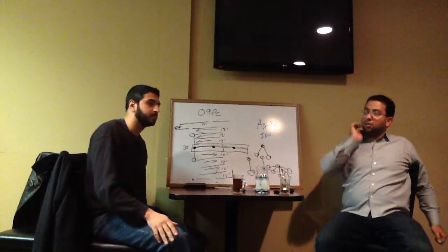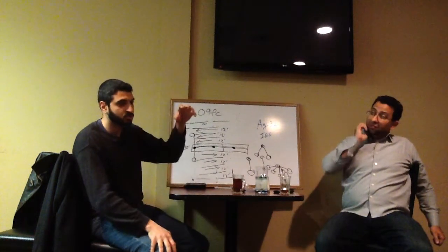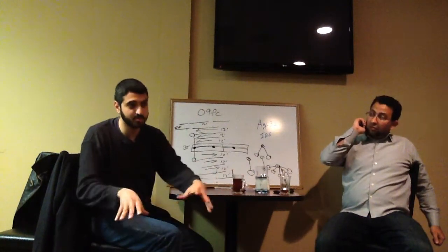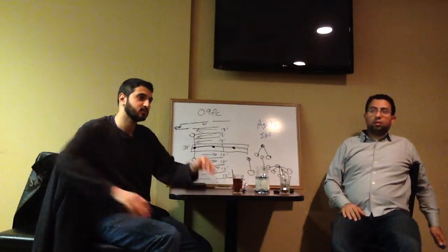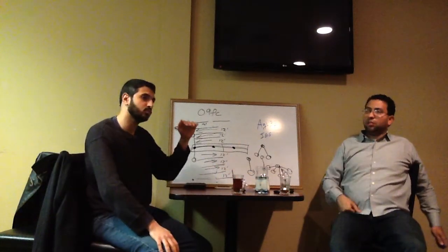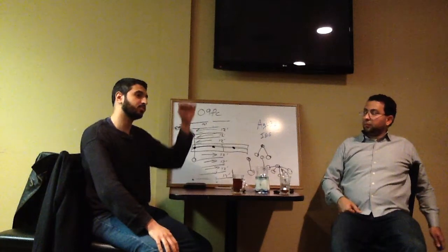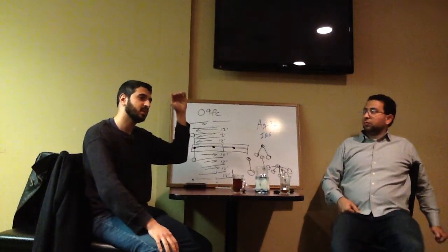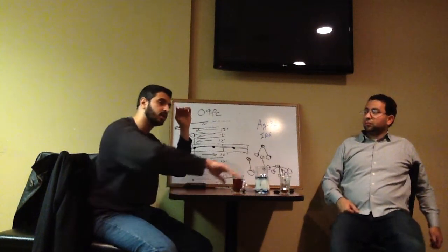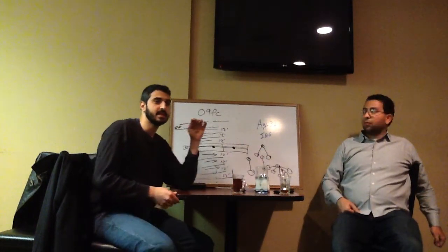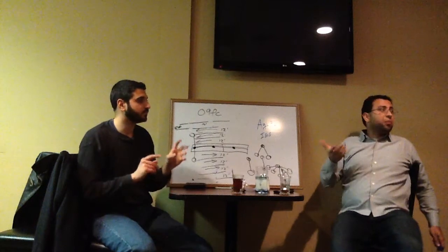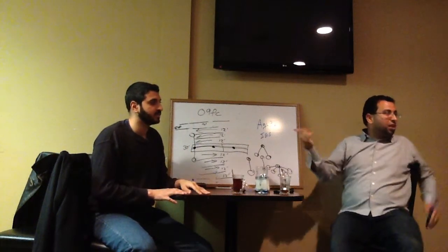Because if you get closer to the ground, you're going to have a really bright spot, and the rest of the area around it is going to be dimly lit and you'll find dark spots. You want to find the appropriate height that's going to give you good even distribution around, the maximum that you can get. This is also from experience and from trying different heights.